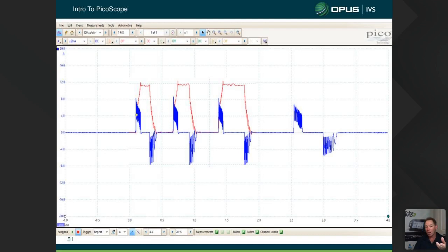You can see at that point we ramp the voltage up to open it, we hold the voltage there, but inside the ECM, we actually reverse the current flow. So the voltage remains the same, but the current flow changes. And the idea of looking at voltage tells us that the ECM is actually sending a signal. The current flow tells us that the piezo injector is responding. So again, we got to that by simply clicking on automotive and following the instructions.